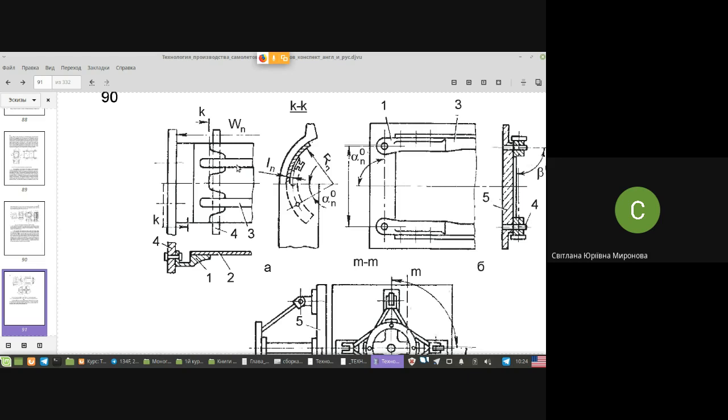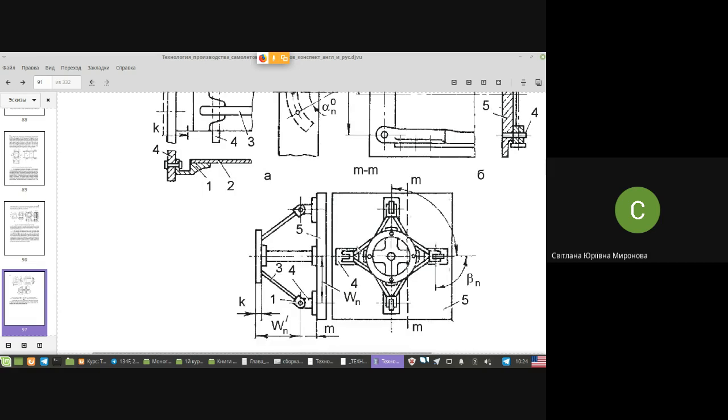And in relation to that question, we have also discussed that these holes' positions, their axes, are extremely important. Here you see the picture of flange junction, here you see the picture of fork type junction. These holes must be aligned since the beginning. They must be coordinated to each other and to the theoretical outlines, and that is why they are located. Parts with such holes are located only in jigs.